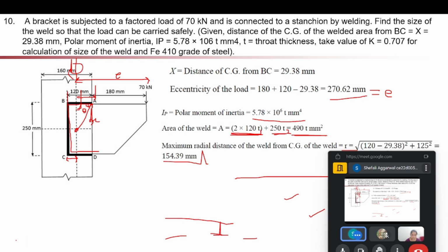They also calculated for the failure of the plate, to find which is governing, so that is fine. But when considering the failure of the plate, there are different lines considered. If the first line has 2 bolts and the second plane has 3 bolts, the first line is considered with 2 bolts in it and that area is considered fine.